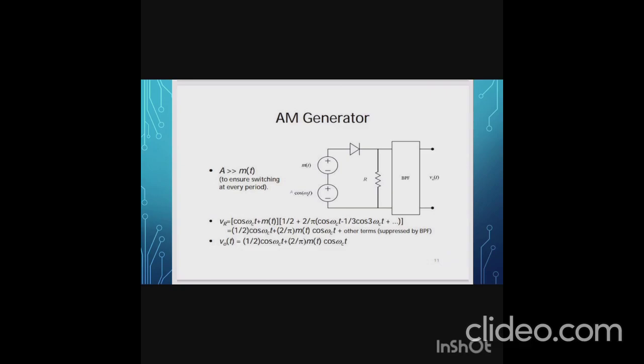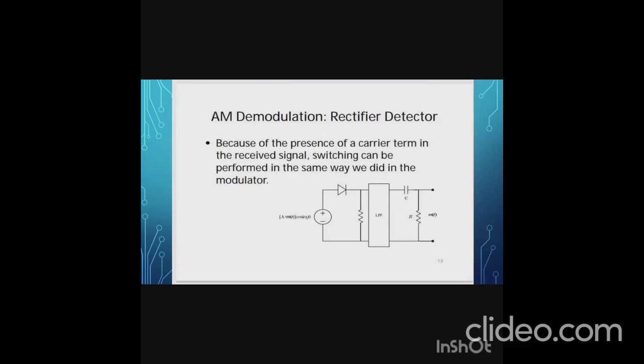Then we move to the single tone sinusoidal modulating signal. Here m(t) is single tone. A single tone is a signal that has a single wave, and sinusoidal means it has sine waves or cosine waves. The modulation index is also defined as the amplitude of the message signal to the amplitude of the carrier signal for single tone. This is written as the equation ma = Am / Ac.